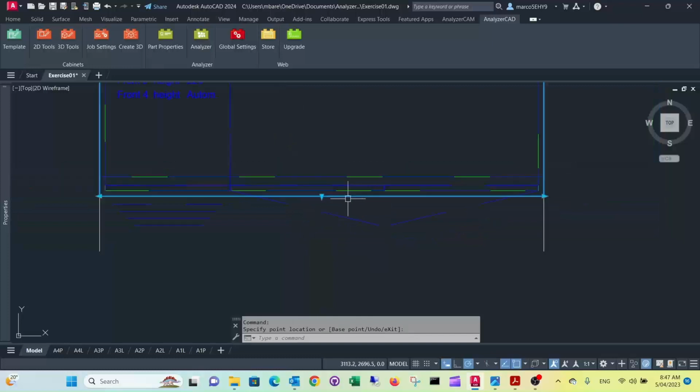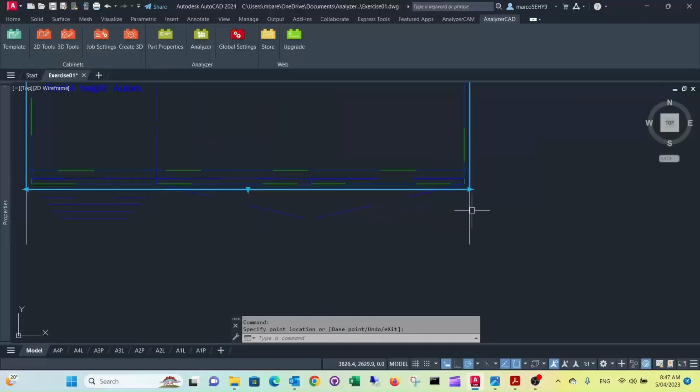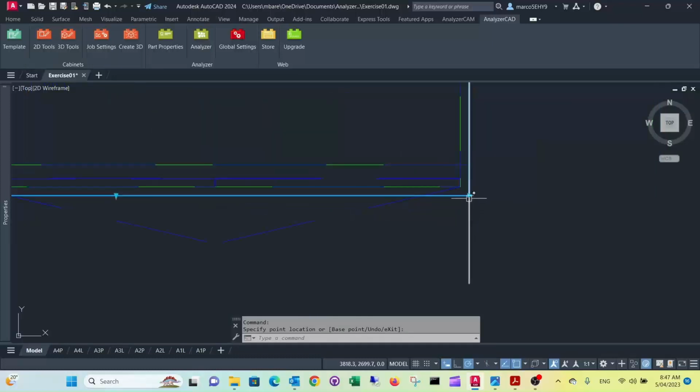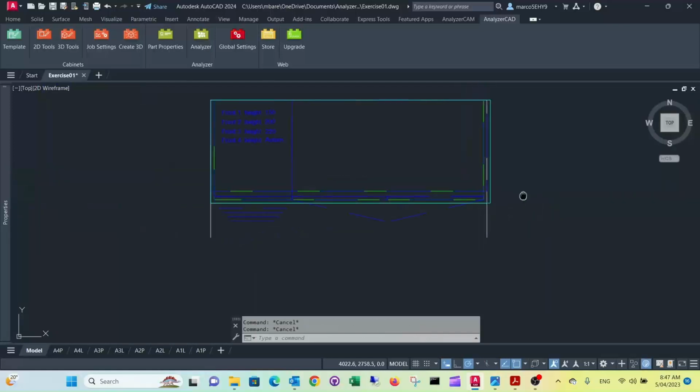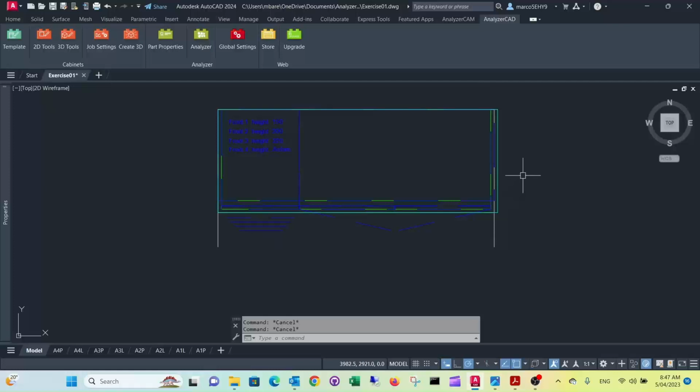Place it on our bench top line. We probably want to have this a little bit oversized, so we can simply make it 20mm longer here, so make it 1620. So that gives us 20mm oversize, so we can scribe it in. So that's basically all to it.